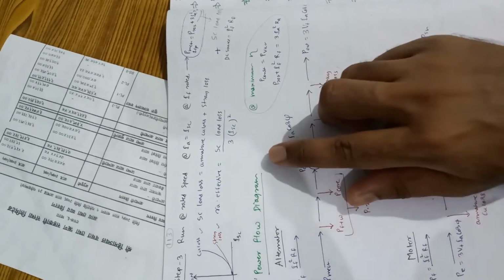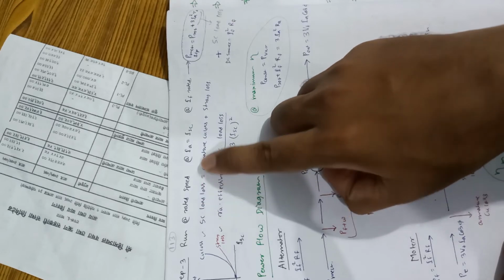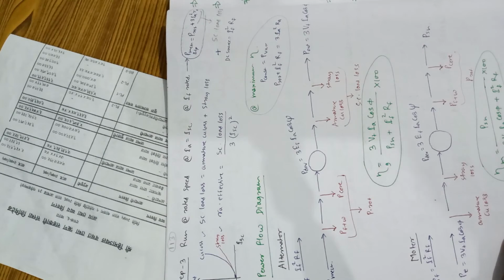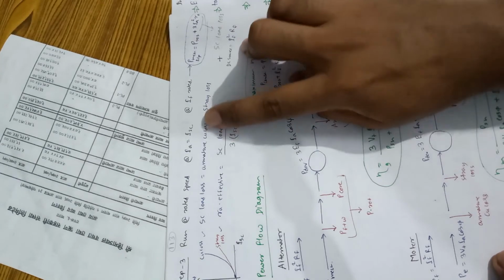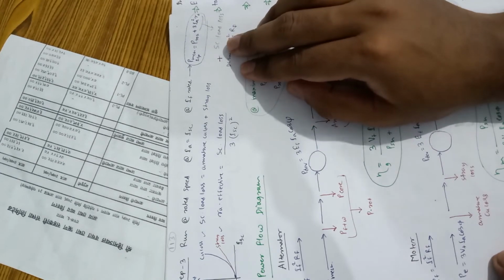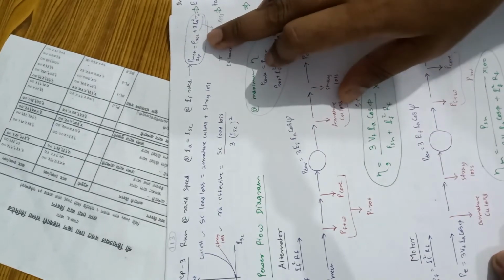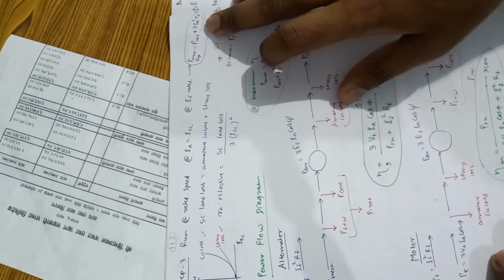When we talk about the third step, what we will do is run the machine at rated speed, at IA equals ISC, and IF equals IF rated field current. Rated field current is given, and IA is also full, ISC. Therefore, whatever the mechanical input will be is the rotational loss, that is core loss plus friction windage loss, plus 3 IA square RA loss.